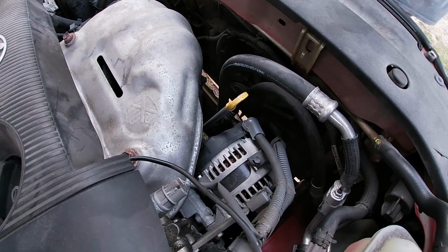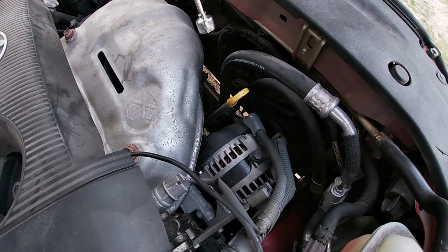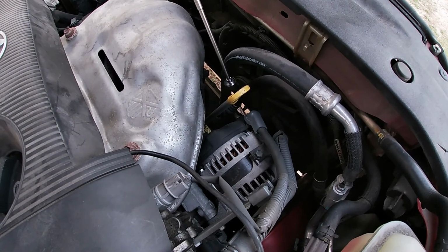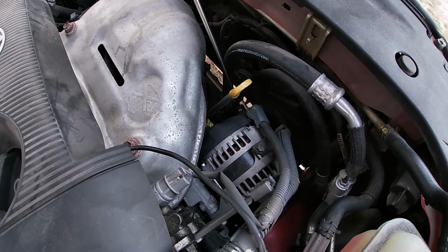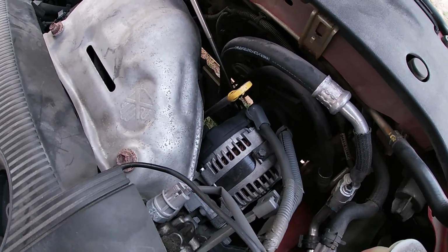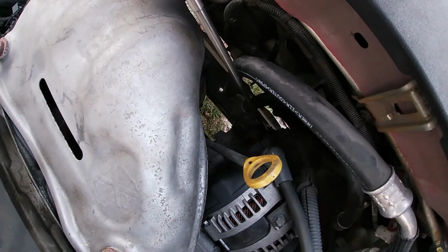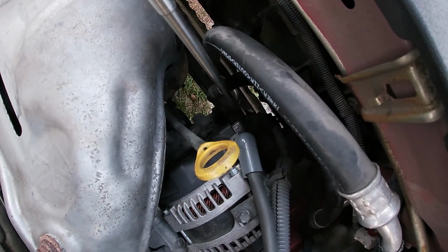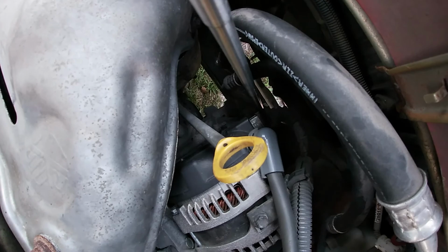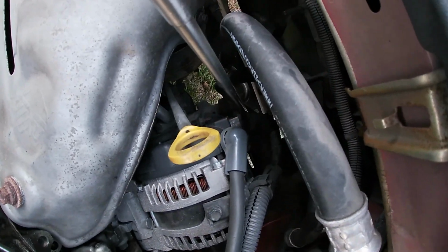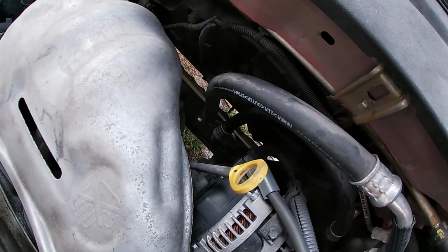So I took the magnetic rod and I placed it on the sensor. Once I placed it on the sensor, you can hear the engine just takes off. Once the engine took off, I went and checked the thermostat I had in the vent to make sure it's blowing cold.